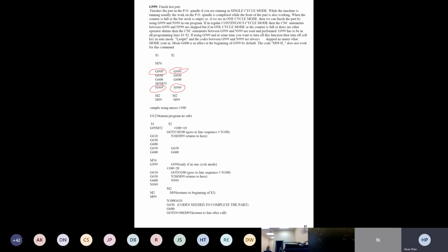At the end of the 1,000 cycles, you're going to have 999 parts complete and one part incomplete in the sub spindle. So in that case, if you want 1,000 parts, you have to hit cycle start one more time to run one more part. But if the material is really valuable, high priced, and you pay a lot for material, you don't want to lose it.